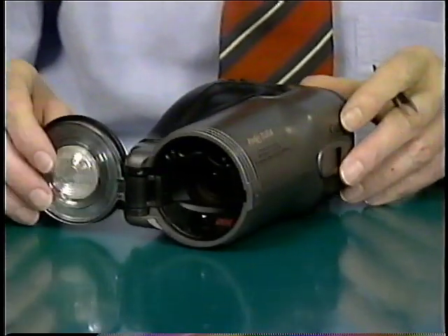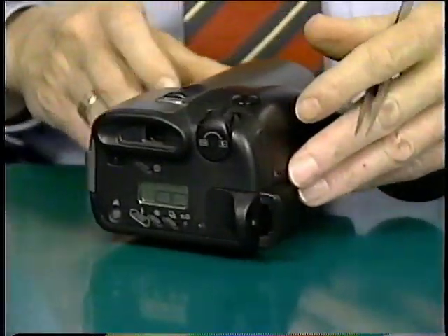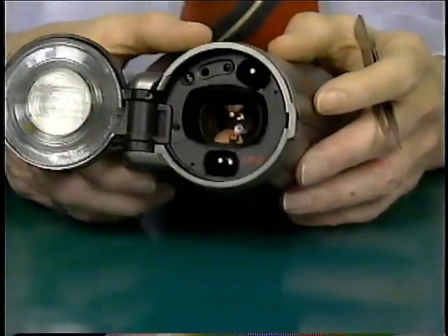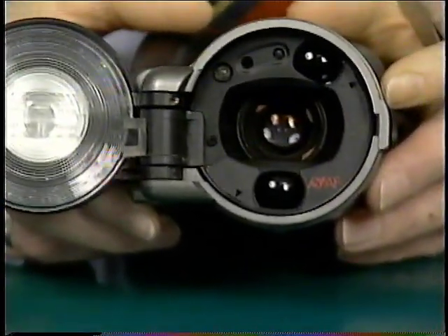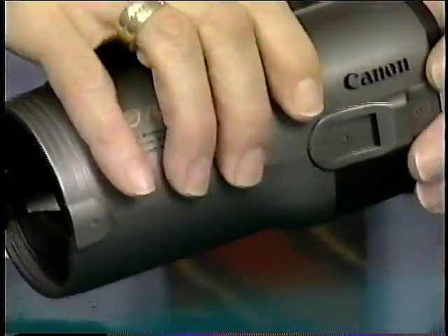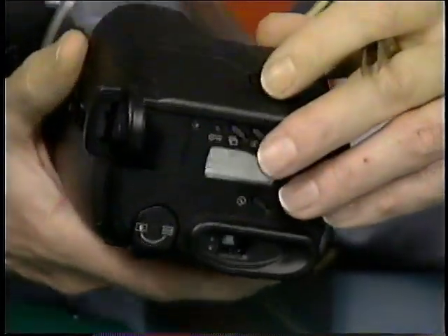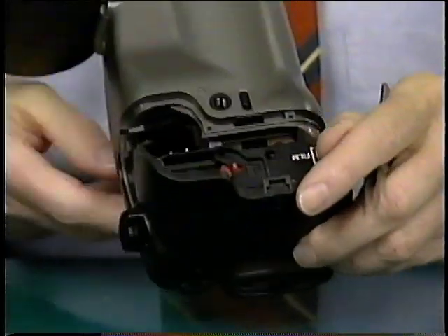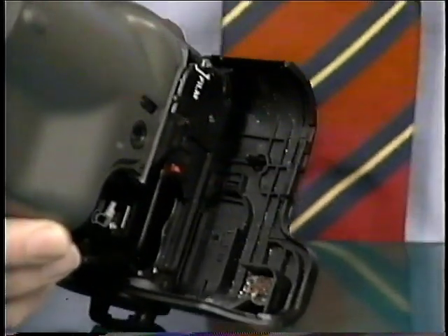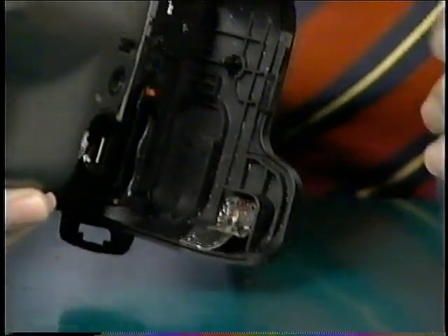This camera looks pretty good again from the outside. There's no significant scratches or dents. It looks clean. Even looking at the front, the lens is clean. Everything looks fine. However, it does have extensive water damage. And the place you're going to look for water damage is on the inside of the camera. Always open the film compartment, because that's something which gets wet. It usually has film in it, which is chemically corrosive when it is wet, and it will leave a lot of corrosion in the camera.